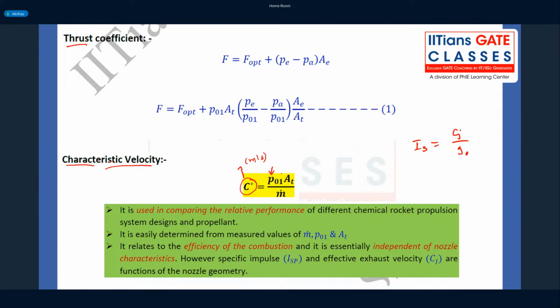the chamber pressure. What we call chamber pressure is the pressure at the start of the nozzle, right? So when you burn the fuel, you will be raising the system's thermodynamic property to a certain pressure level P naught and a certain temperature level T naught. Why do we need to improve the P naught?